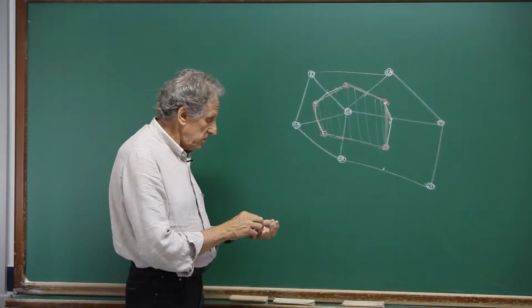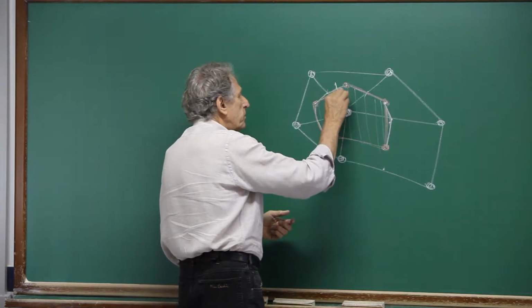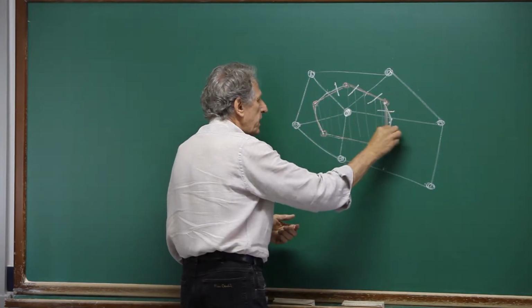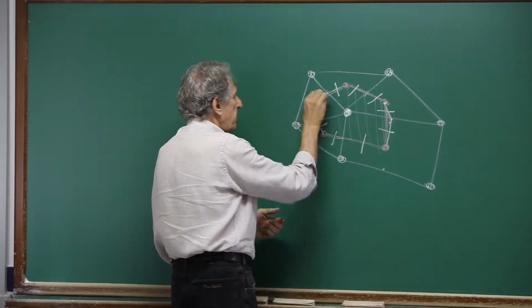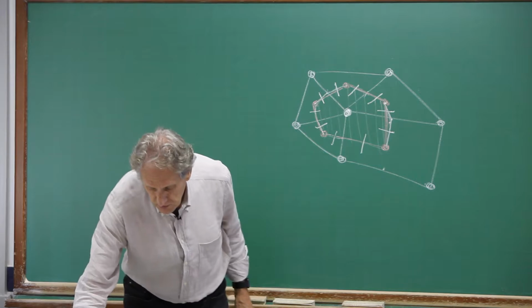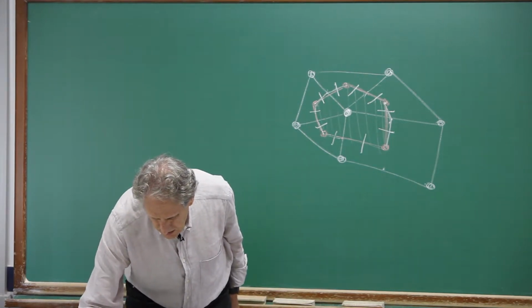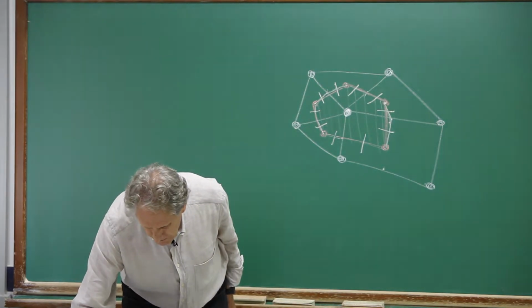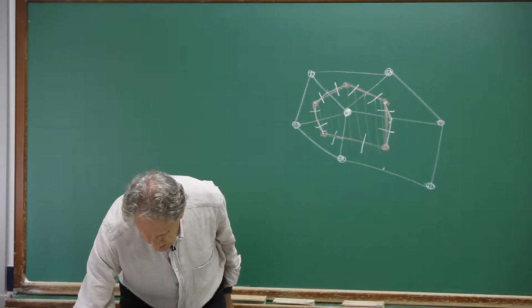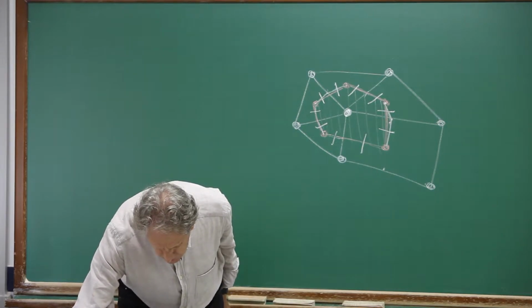This is our control volume, and here is our unknown. And we are going to perform flux calculations in all these positions. So the construction of the control volume for the element-based is joining the center of the elements with midpoints.